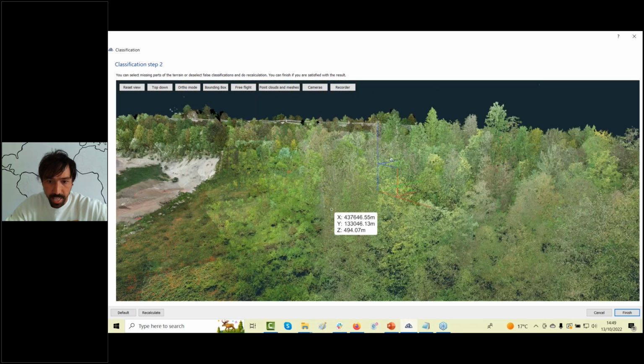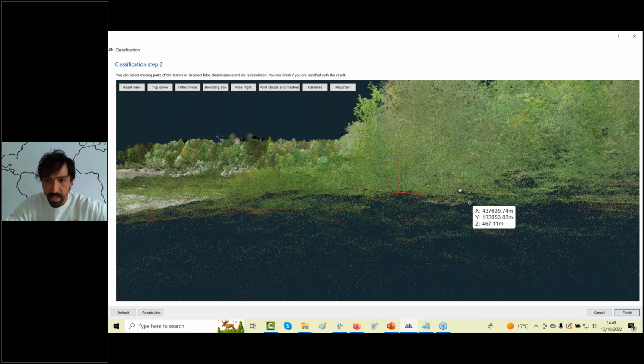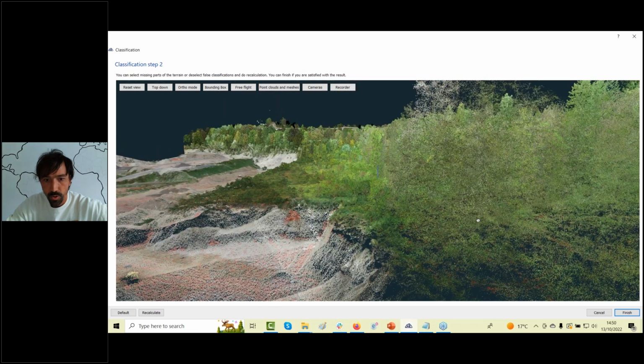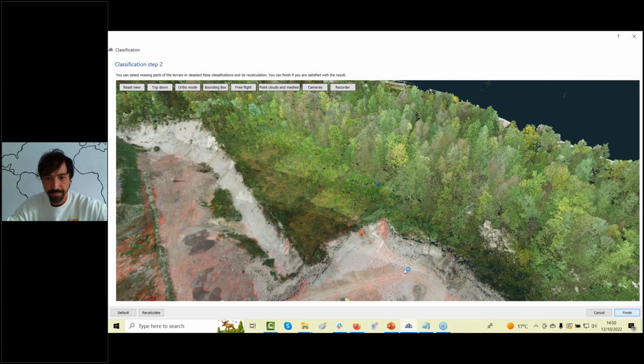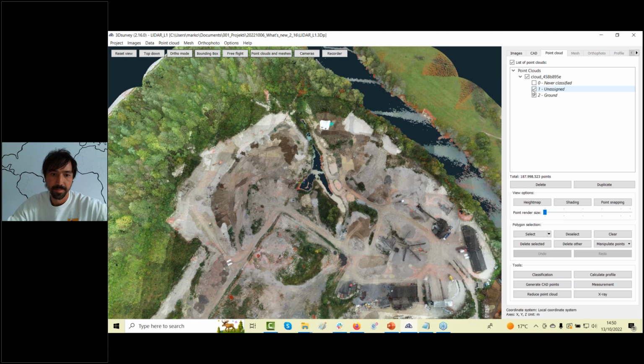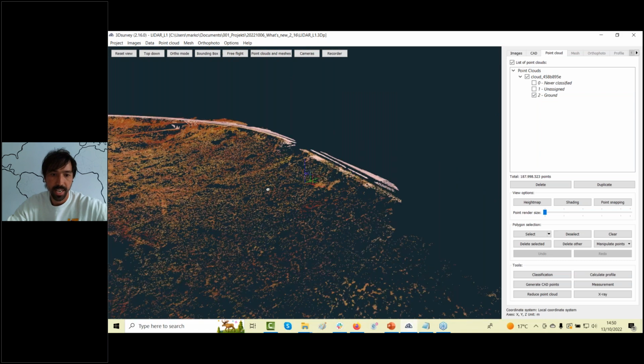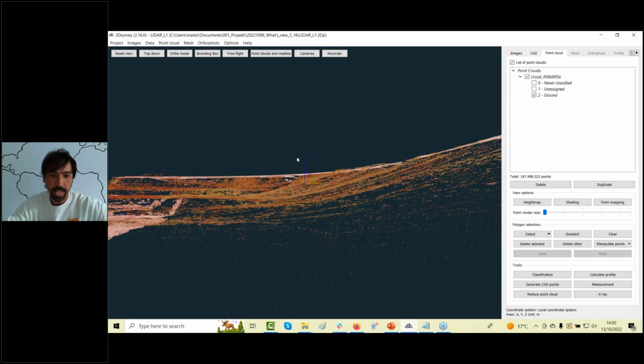And what's interesting, also here beneath the forest, we found a few terrain points. If I go to finish to see the result in 3Dsurvey, and deselect never classified and deselect unassigned, you'll quickly see that we successfully found quite a lot of points under the trees.